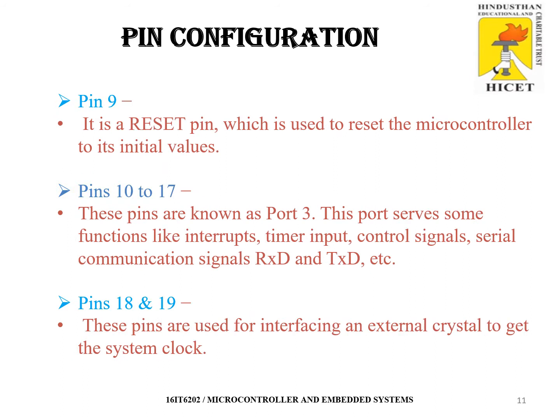Now coming to the next pin, that is pin number 9. What is the use of pin 9, RST? RST is nothing but the reset pin, which is used to reset the microcontroller to initial values. That means if the microcontroller is performing some task, for example, after execution of one cycle or one program, it should reset to the initial values. That means all values should become 0, 0, 0, 0.